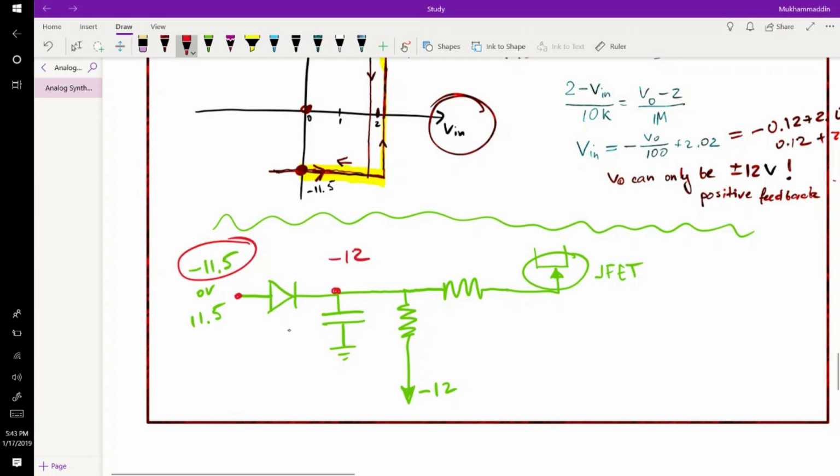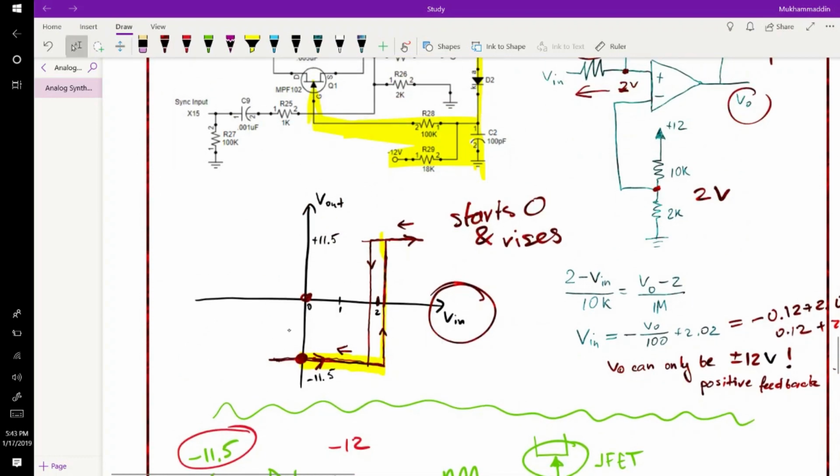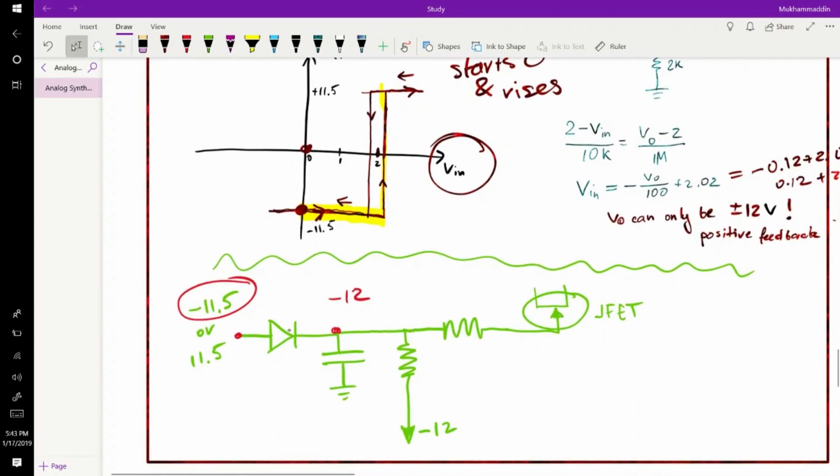And this diode is a regular 914 diode, and the forward bias voltage for this is around 1 volt if you look at the datasheet. So there is not enough voltage drop across this diode to forward bias it. So this diode is not conducting, and at this node you have negative voltage.